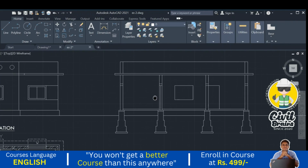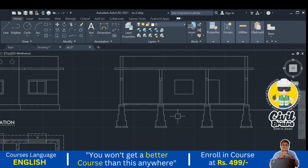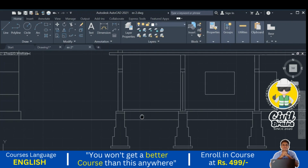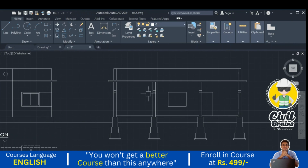Next we have shown the plinth. We have shown the foundation, next plinth, about the plinth PCC, then wall, superstructure, and parapet, and also the plinth and the floor and door, all the things are shown. Now we need to identify the things. How to identify the things? Identify in the sense we need to hatch the things. By hatching the things, you will identify what this is.